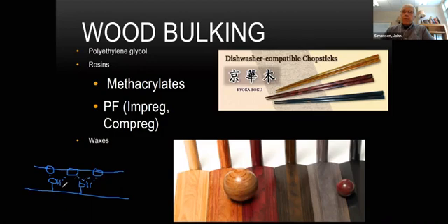Sorry about that first one. Okay, and this should be like this. So this is what happens with water and wood, right? The water is going to hydrogen bond to the hydroxyls on the wood surface. But when polyethylene glycol lays down, in order for the polyethylene glycol to be removed from the surface, you have to release all of these hydrogen bonds at once.